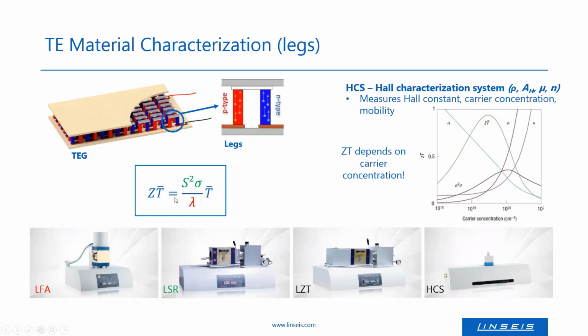Linseis offers 3 different Hall characterization units with either permanent magnets, a more powerful electromagnet, or with a rotating Halbach magnet, which allows an oscillating magnetic field. And all of these 3 setups are equipped with integrated and optimized measurement electronics and can be upgraded for high temperature measurements up to 700 degrees Celsius, as well as lock-in amplifiers for noise-reduced AC measurements.